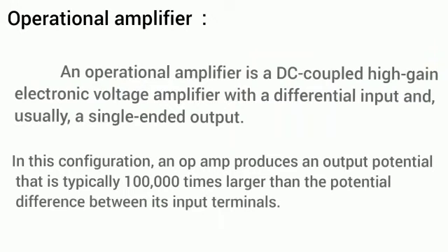Operational amplifier. An operational amplifier is a DC coupled high gain electronic voltage amplifier with a differential input and usually a single ended output. In this configuration, an op amp produces an output potential that is typically 1 lakh times larger than the potential difference between its input terminals.